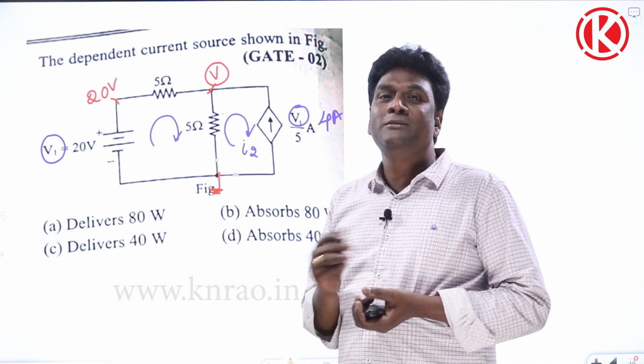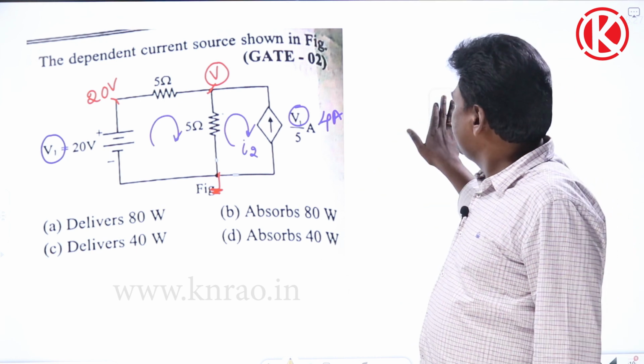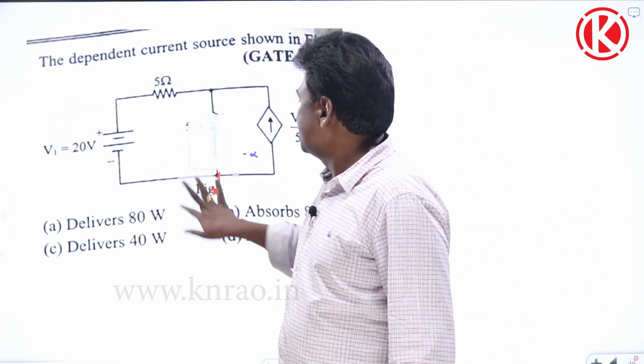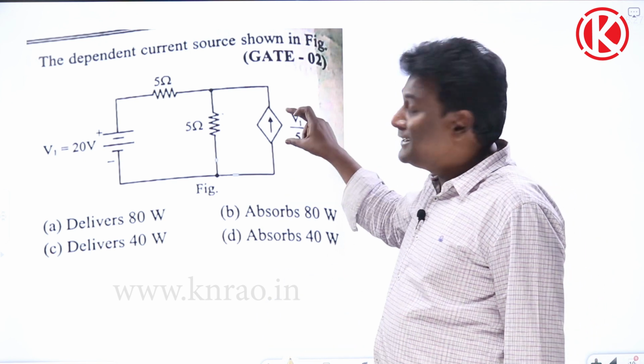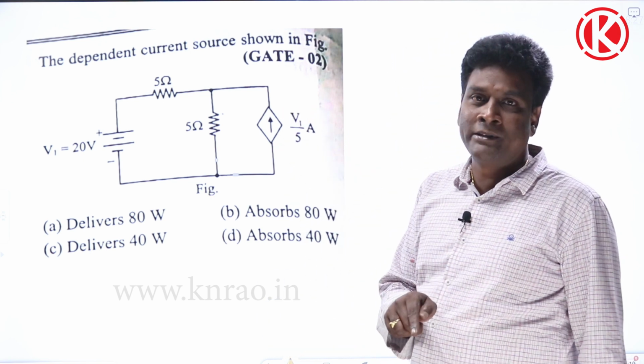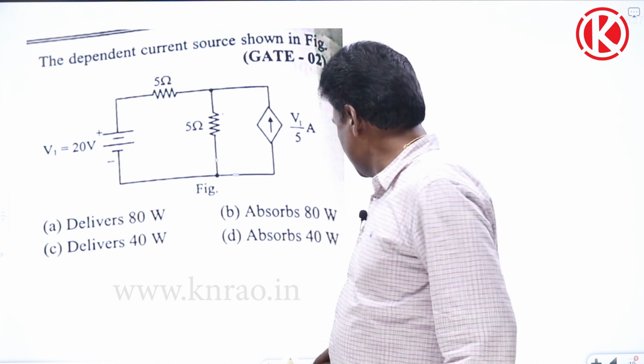Now again, which is better? Because from equations point of view, both are same. Now let us think of which is better. What is the output requirement? Current is known, voltage is the output requirement. So directly voltage can be found by applying nodal analysis. So apply nodal.